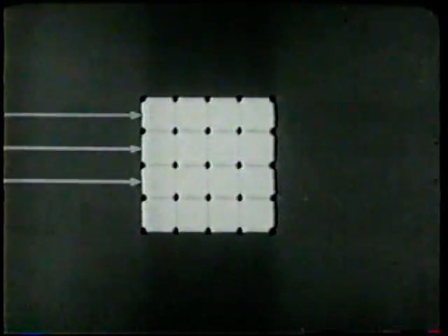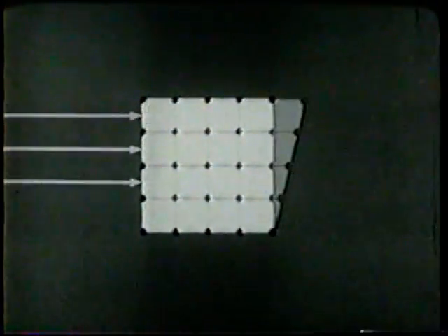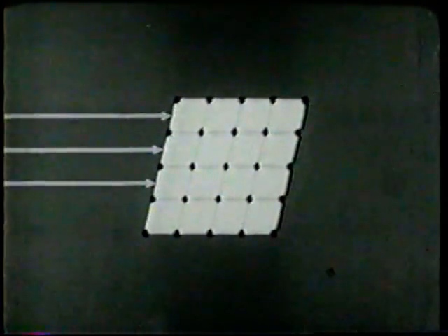The second type, plastic deformation, occurs when the applied force is increased beyond the elastic limit of the crystal. The space lattice yields. In the process of twinning, the lattice is deformed by some fraction of an atomic spacing. In slip displacement, the blocks of atoms move an integral number of atomic spacings.